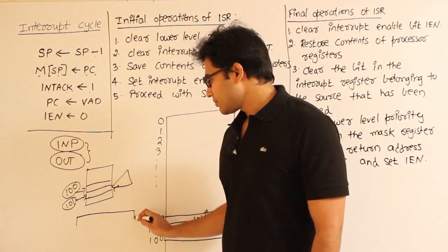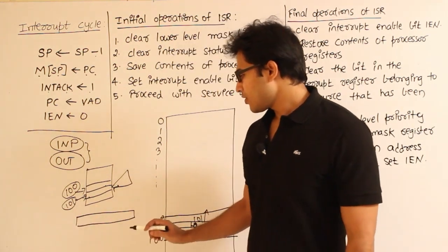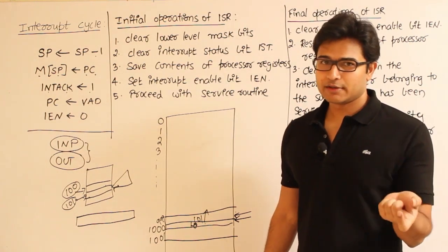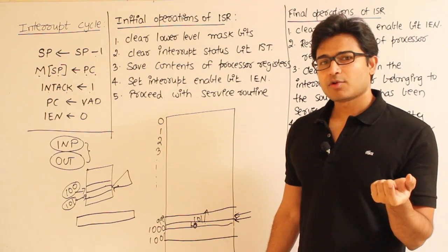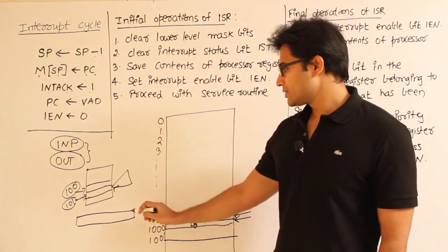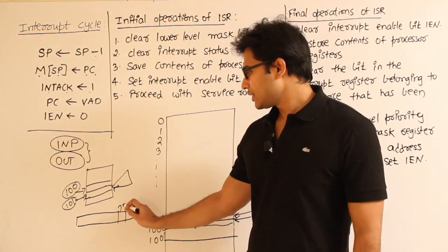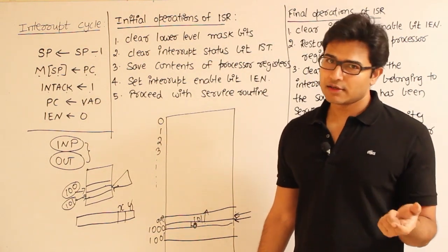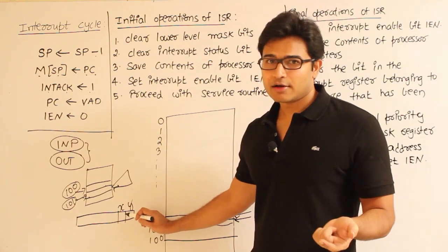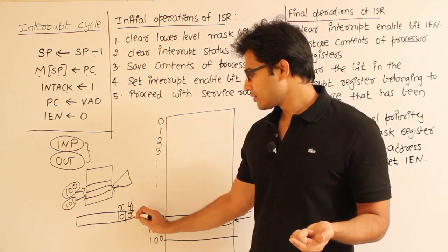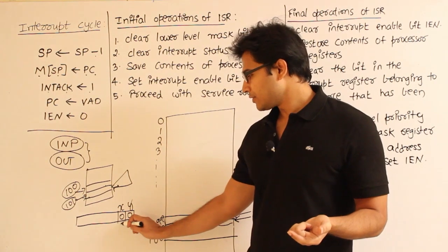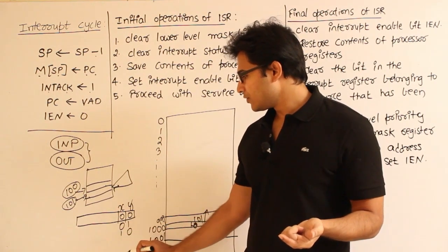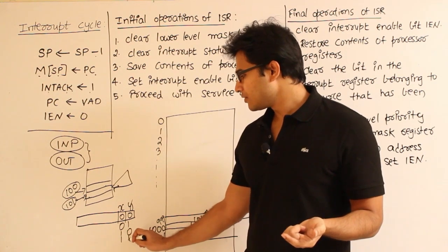Now in most computers, how it will be implemented is, we have seen it, the register has many bits, and the priority encoder, you please refer to the diagram, is providing us with 2 bits, x and y, isn't it? In case the interrupt is given by the hard disk, then it will be 00, right? Otherwise if it is a printer, then it will be 01. If it is a reader, then it will be 10. If it is a keyboard, then it will be 11.